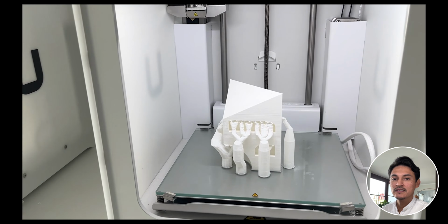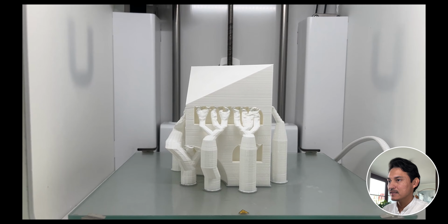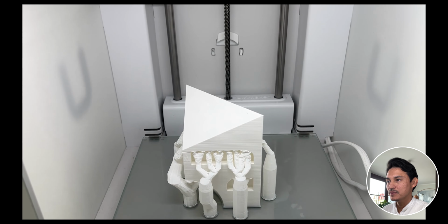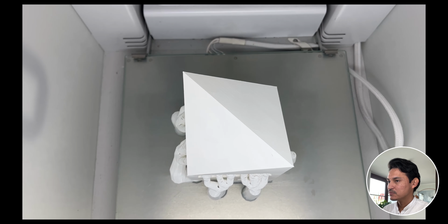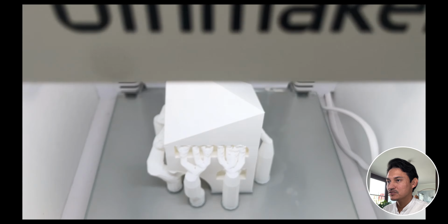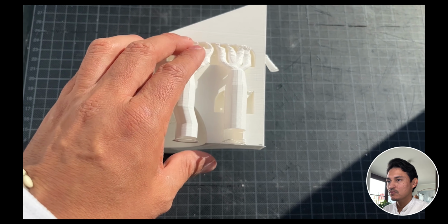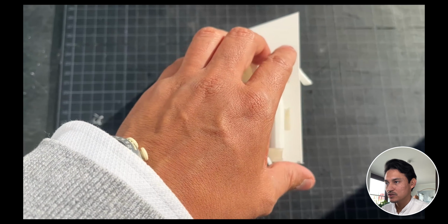Once the 3D printing is done, you can remove the glass plate from the 3D printer and then carefully take out the 3D printed piece. Better if you use eye protection because some of the support pieces may fly away, and if the piece is really hard to take off, you can cool down the glass plate with some cold water. Then it's easy to remove it.